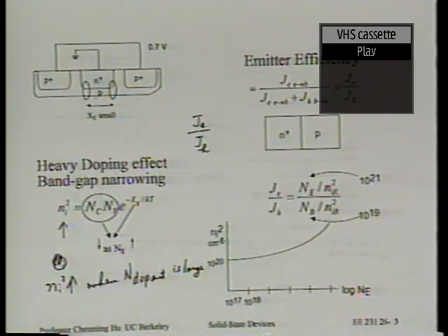Uniform germanium concentration, exactly, right? We have uniform germanium concentration. It definitely still gives us a lower band gap, solves this problem. The DC gain is good, but there will be no drift field, so the cutoff frequency would not be very high, okay? Both are important.